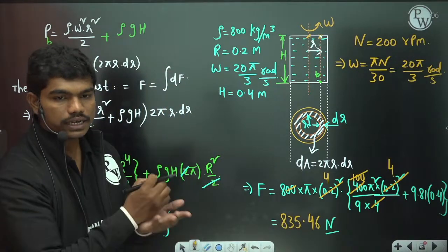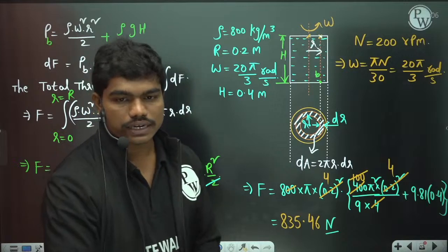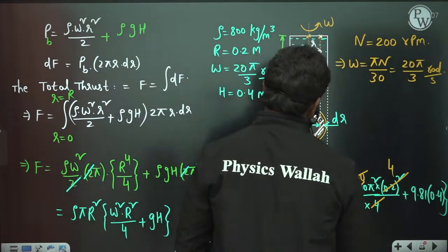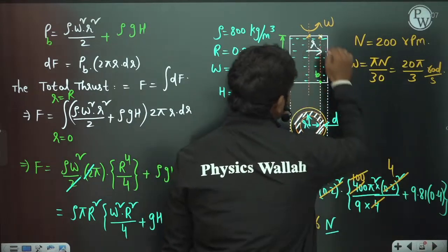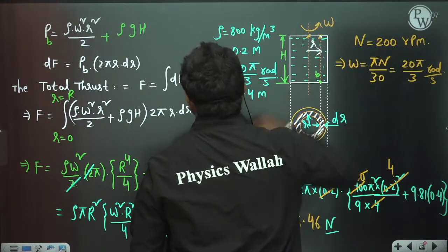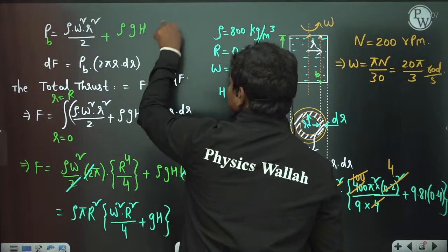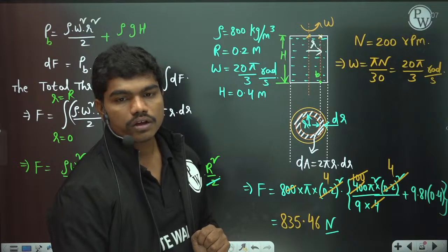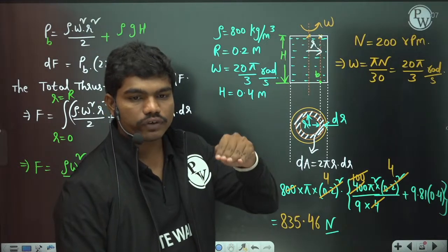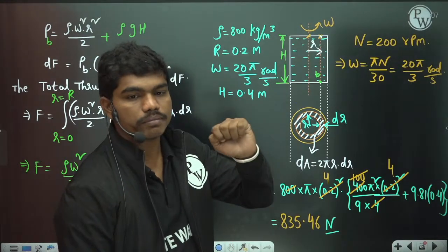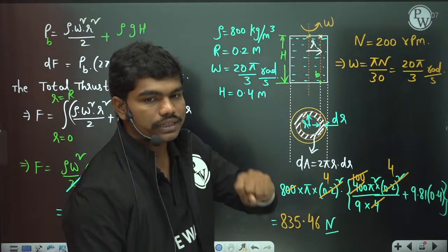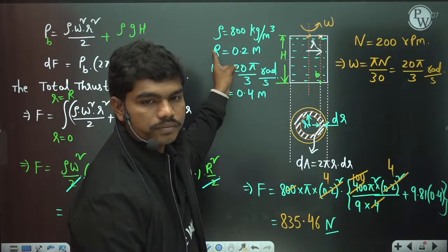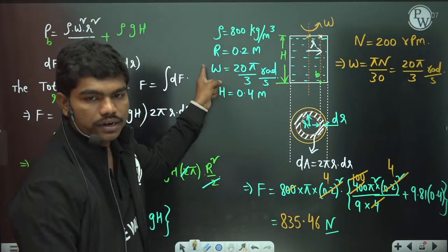So this is basically the force acting on the container. Now, if the container is open, then what happens? Please explain, sir. Yes, if the container is open, you have the same analysis, but of course along with that you also have the atmospheric pressure, so plus P atm will be added at this location. Since the container is closed and completely filled with fluid, the free surface is at 0 pressure, which is what we are assuming. But if the container is open, then we have P atm also here.